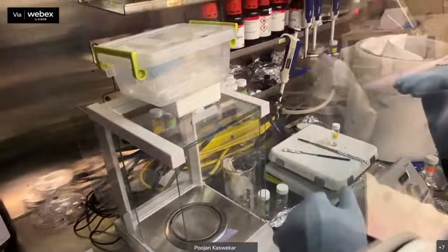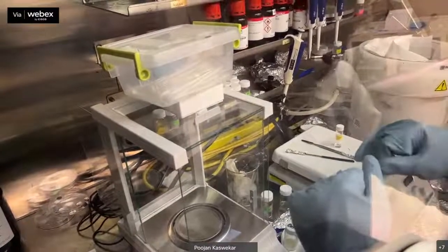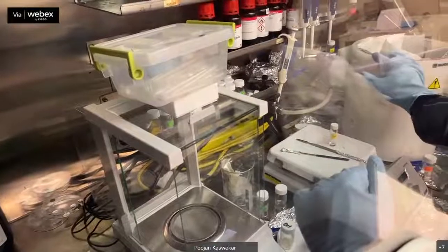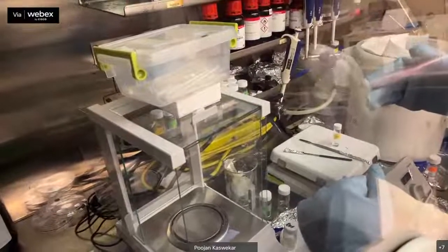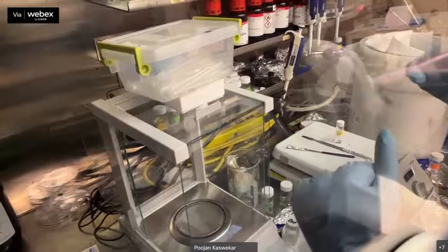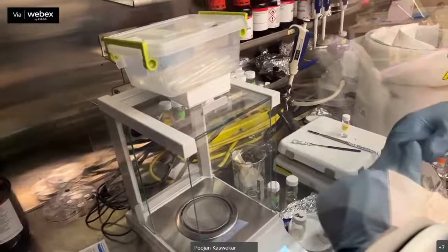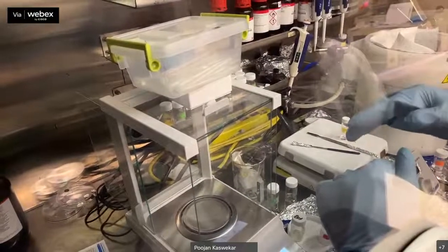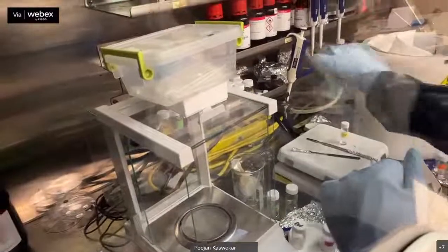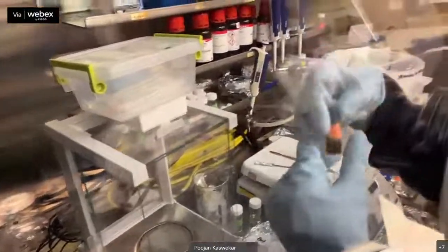As you know, we can control the perovskite thickness and everything else from the spin coater, and you can control the band gap of the perovskite using the material. Suppose you take the most common MAPbI3, that is 1.51 electron volts. That's the solution we prepared here.